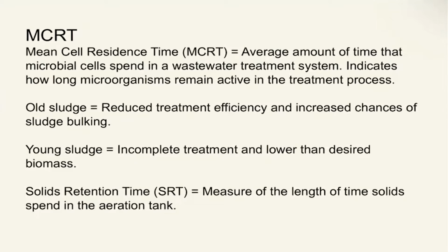Another parameter that can be used to determine wasting and reuse rates is solids retention time, or SRT, which describes the amount of time solids spend in the activated sludge treatment process. SRT was previously more widely used than MCRT, but from what I have seen, state operator certifications typically utilize MCRT more frequently. There are many instances when the equations are used interchangeably in reference material as well, and it is important for anyone using this video as a study guide to make sure they compare the equations we use and the equations they need to be using and make adjustments as needed.